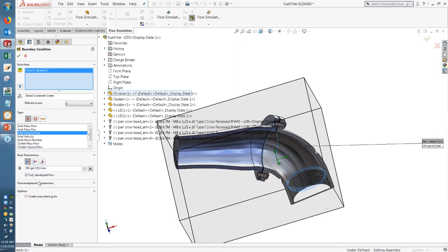And that tells the simulation that the hydrogen will probably already have a nice turbulent boundary layer and a parabolic velocity profile, all of those traits that would be associated with flowing down a long tube or channel. And so that way I don't have to look up what kind of velocity profile I would want to input manually, or even include that part in the assembly. I can just check that box and it'll be very similar in realism.